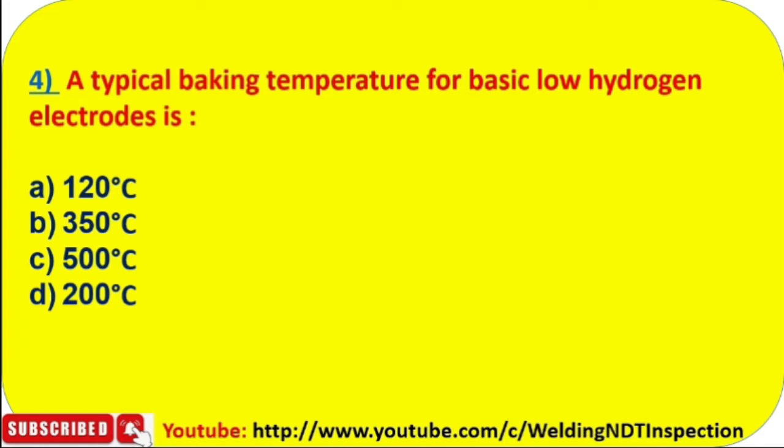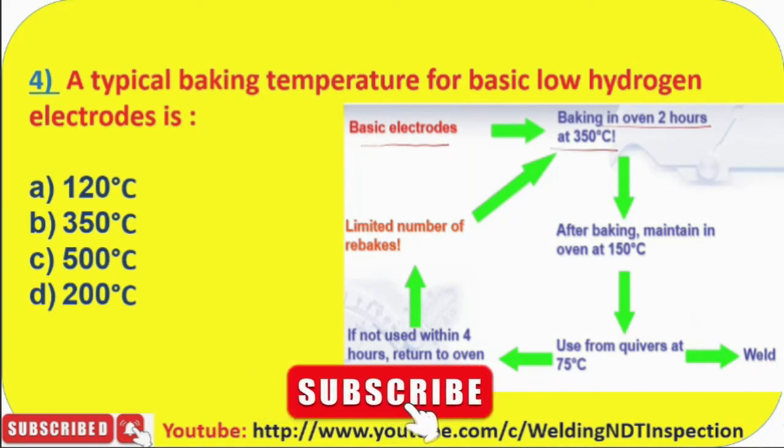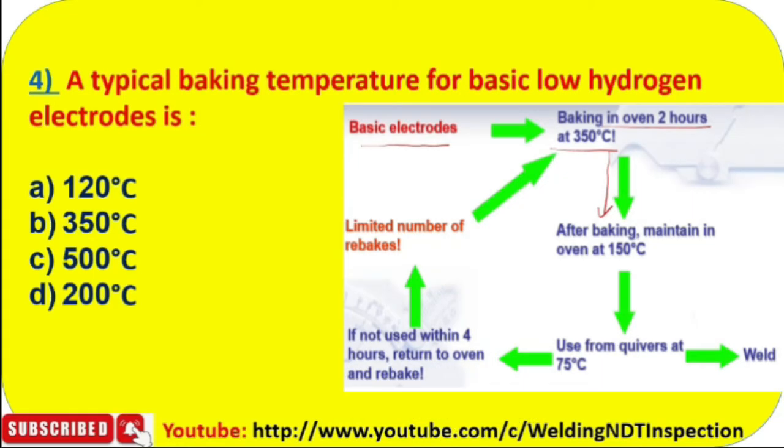Those people working as welding engineer, welding inspector or QC inspector should know this information. You see here, the basic electrode is baked in oven for 2 hours at 350 degree centigrade. After baking, it is maintained in the oven at 150 degree centigrade, or sometimes 100 degree centigrade also, depending on client requirement. If the procedure mentions 100 degree centigrade, or the manufacturer recommends it, then it may be 100 degree centigrade.